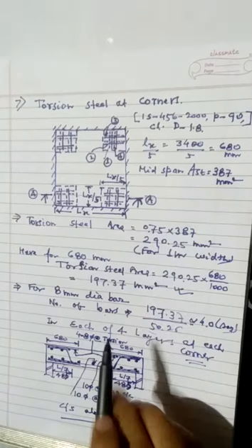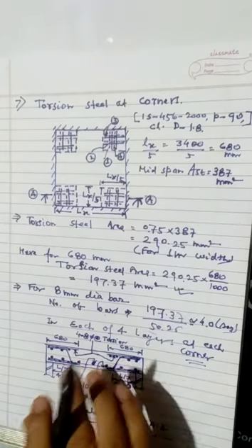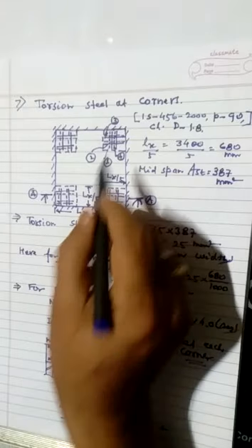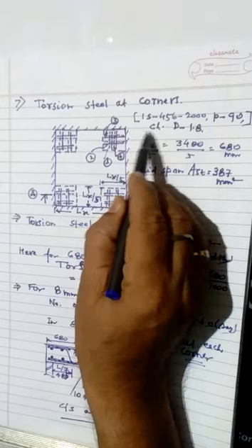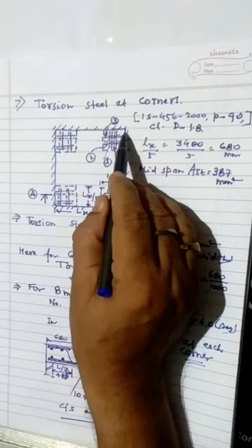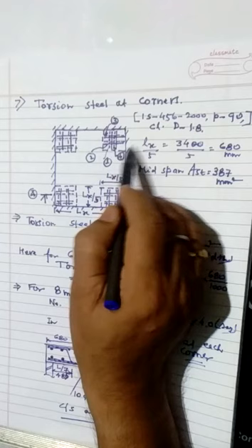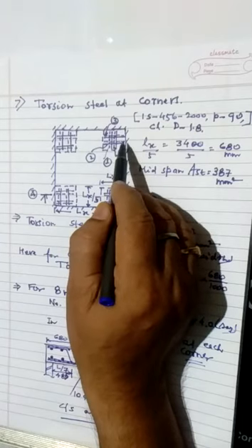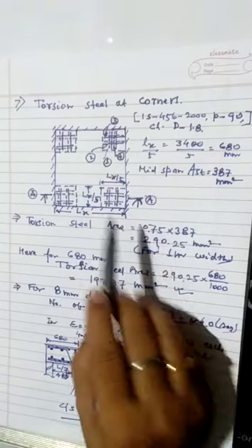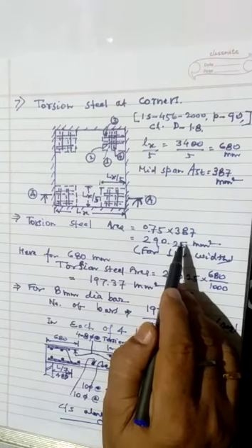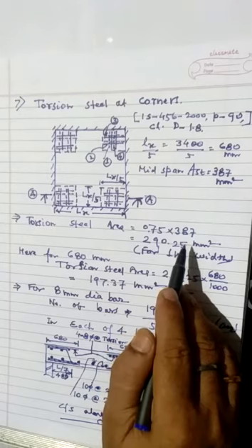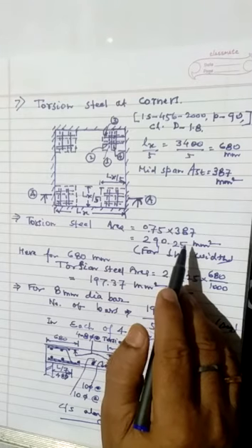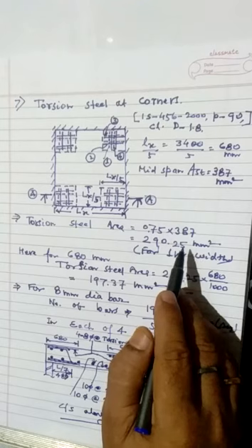The area of the steel is provided. Now suppose there is a corner where only one edge is discontinuous and the other is continuous, at that corner we provide 50% of the torsion steel as provided at such corners. So according to the situation in the plan of a building, the corner steel will be provided, and that is very important to restrain the corners from lifting, and that has so many other advantages in the slab.